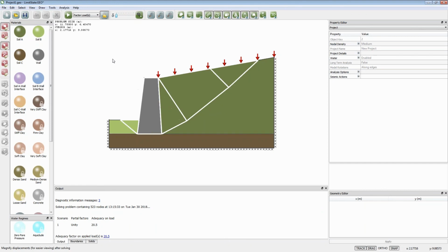Now, conventional calculations often ask you to check against sliding, overturning, and bearing as 3 possible failure modes out of effectively an infinite number, because you could get a combination of sliding, overturning, or overturning and bearing, and so on. So for hand calculations, you can't be expected to calculate all the different combinations. So you're normally asked to calculate sliding, overturning, and bearing separately. And if those pass, then it's assumed that any intermediate mechanism is then also passed.